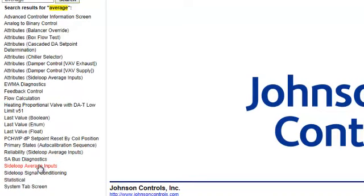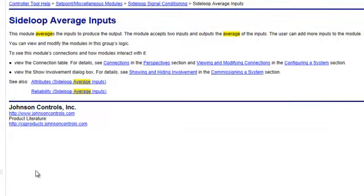Let's see what it says it does. This module averages the inputs to produce the output. The module accepts 2 inputs and outputs the average of the inputs. The user can add more inputs to the module. This appears to be what I want. So now I'm going to close Help, go back to Controller Tool, right mouse on Setpoint Miscellaneous, and add a new module. So there's a filter here, and this really makes it easy because I'm just going to filter by putting side loop.